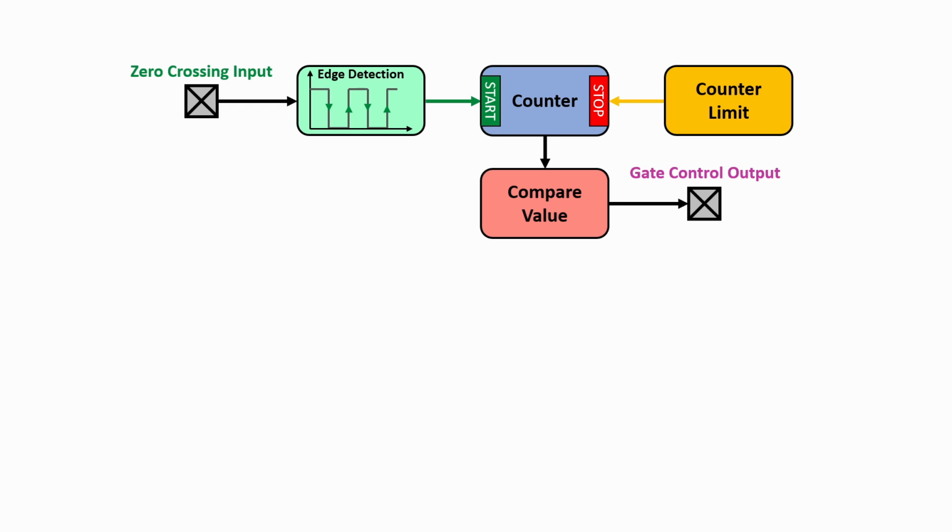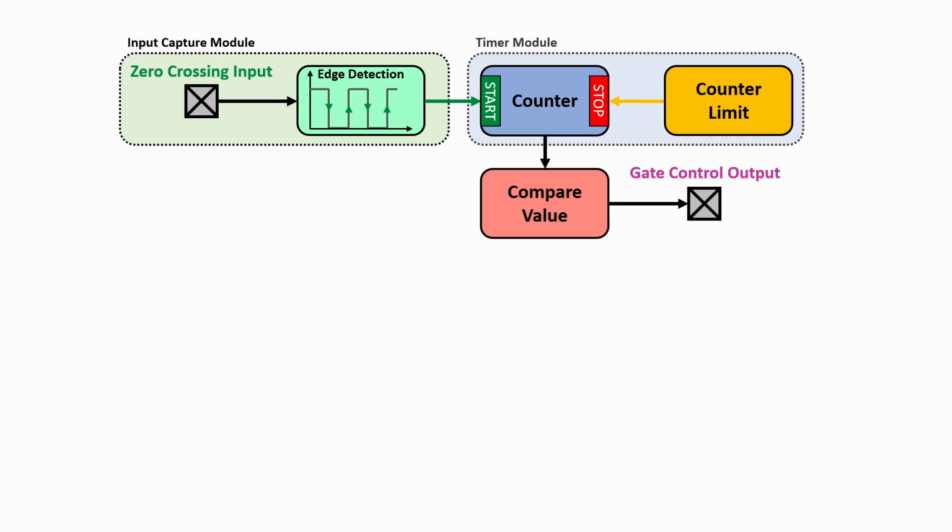Luckily, all these fundamental blocks and components are available in almost every microcontroller. An input with edge detection is called input capture module. A counter with counter limit is called timer module. And a counter compare value that can control an output pin is called output compare module.